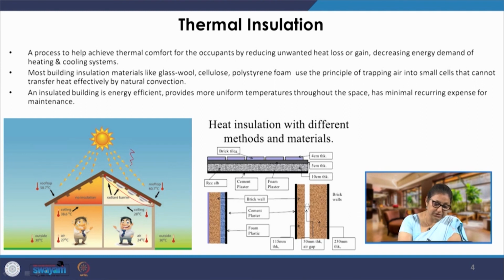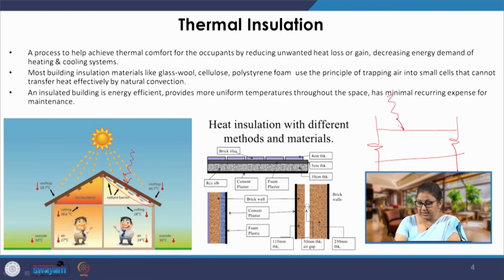The radiation is going to be incident on this roof. If I take this roof slab as the section here, when there is incident radiation on this roof, which is when the sun is out there, plus we also have a higher temperature outside, this surface is going to receive heat through radiation as well as conduction.